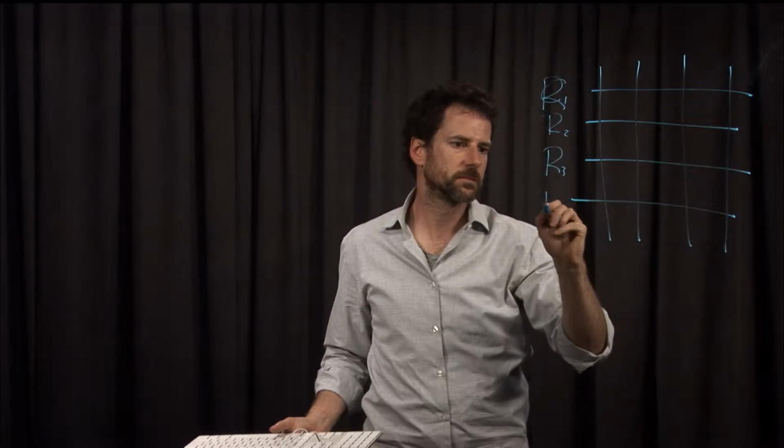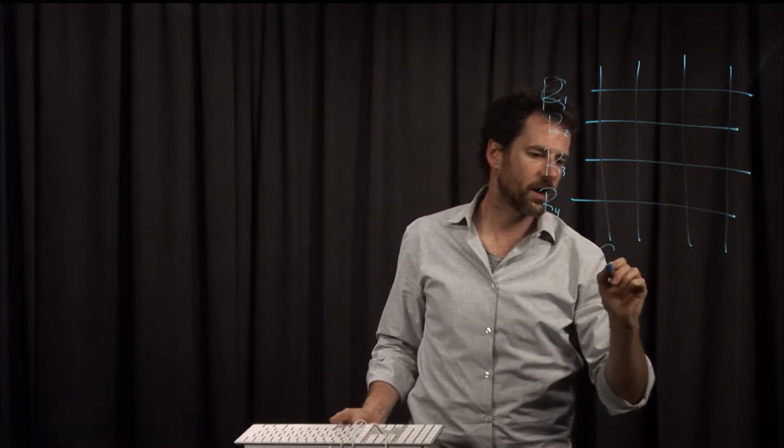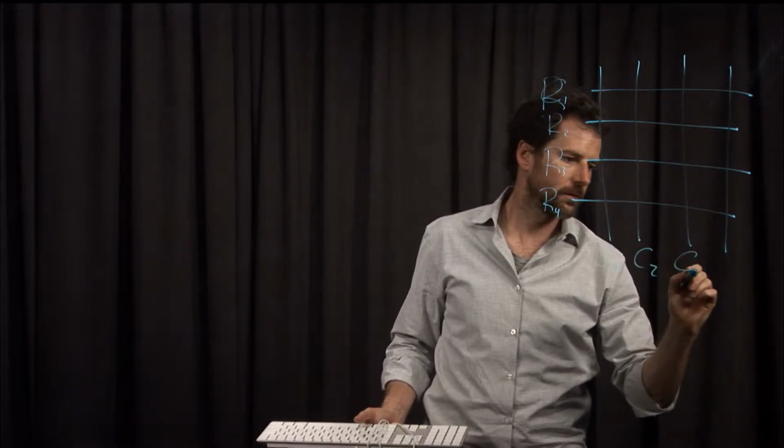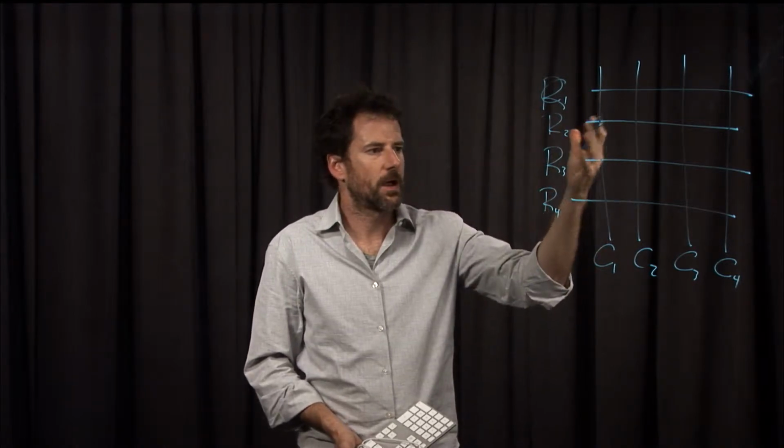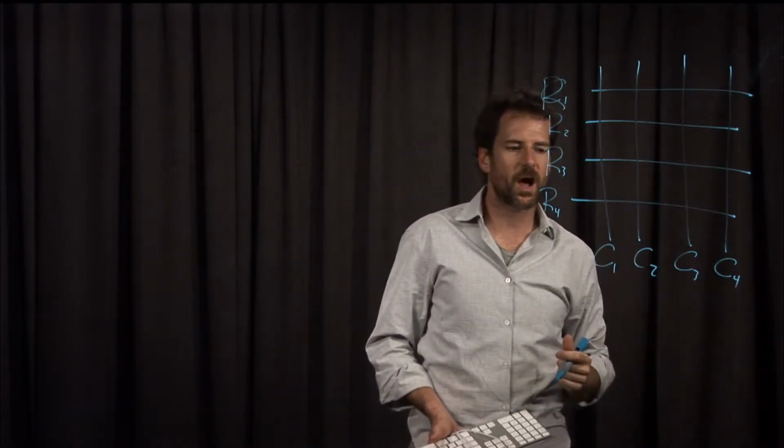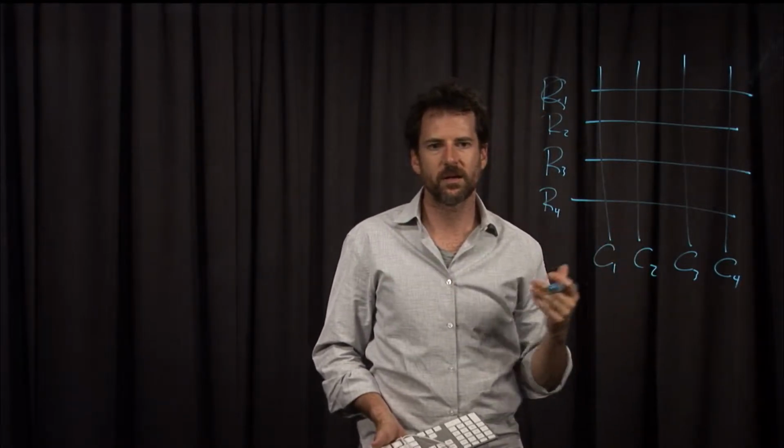So if we take all of these keys and we pop this open, what we'll see under the hood is that we've got a lot of rows and we've got a lot of columns. These are the wires that we saw inside the keyboard. So we have our rows, and we have the columns here. Altogether, we might have 8 or 9 rows and a dozen columns. It'll depend, obviously, on the exact keyboard layout.